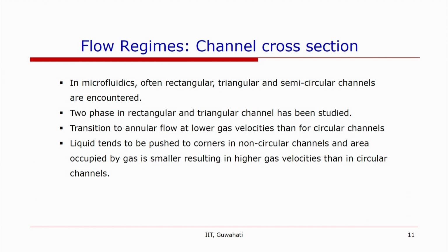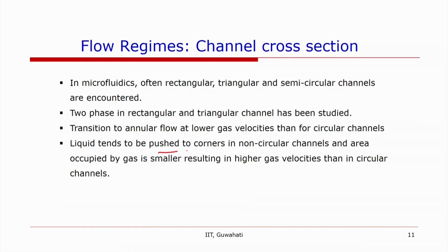In all these non-circular channels, they have sharp corners, and the liquid goes to the corners and stays there, it remains stagnant. So, the liquid tends to be pushed to the corners in these non-circular channels. So, now the gas has less area available in the channel to occupy.